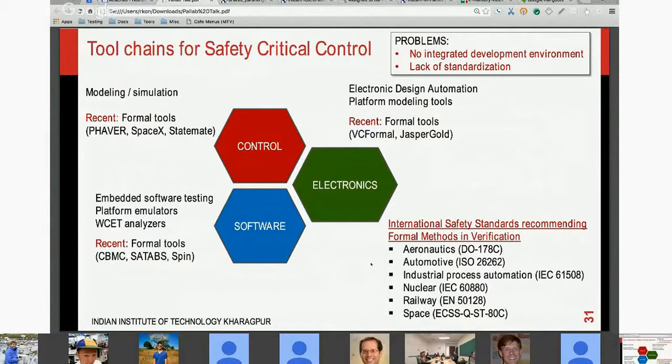So then how do you handle safety critical software which is going to go into your embedded application? And increasingly we are going to put more and more embedded applications in the healthcare sector, for example, for drug delivery and other types of safety critical tasks. We need to prove that the software is exactly correct, right? So how can you prove that a software is going to work for all possible inputs? The key to such problems is that you treat the inputs as symbols. You don't assign values to them, right?